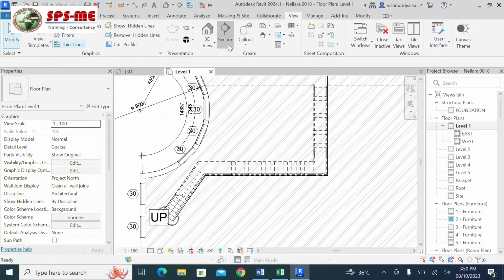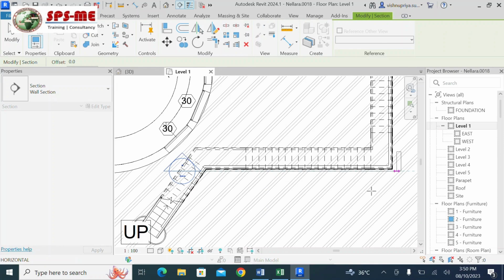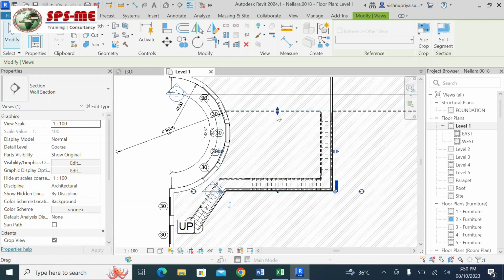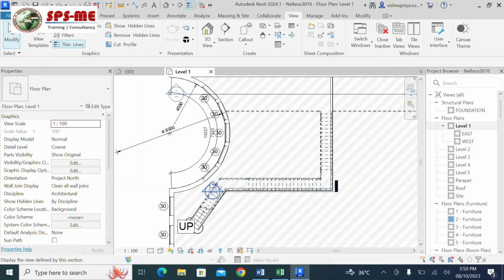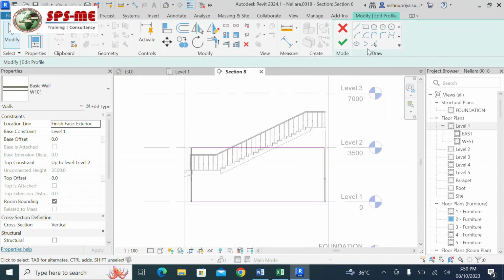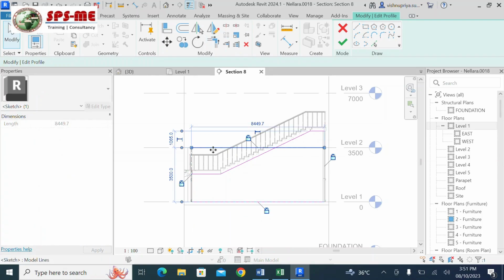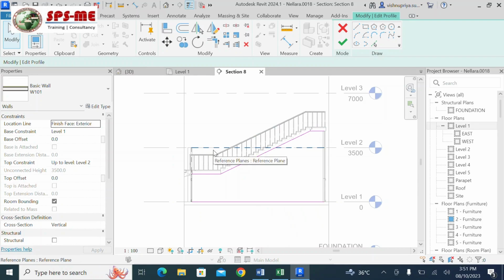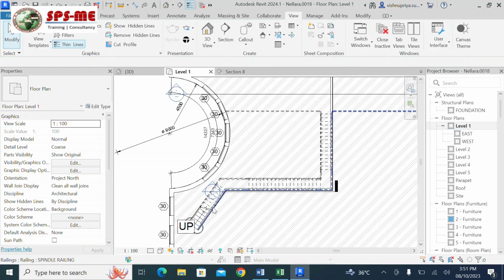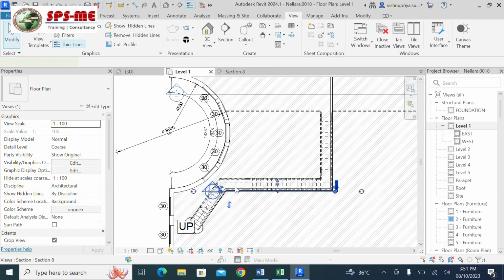And we are going to create another section over here. Then just double click the wall, again you can do pick lines, I do here, here and this side, and we have to do the trim, and this extra lines that we have we can remove. So your sketch should be a closed sketch, that is important. Click finish. Then again you go to this and remove the sections.